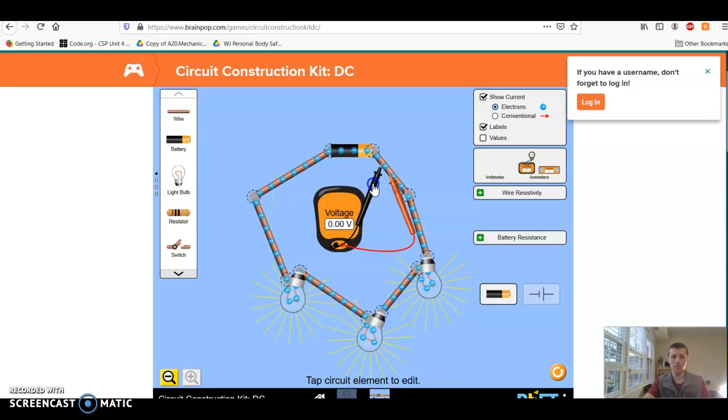Now, something interesting happens if I switch these two. You'll see I still get 20.5, but now it's negative. For our purposes, it's not usually going to matter whether the voltage is negative or positive. It just determines which way the electrons are flowing. So this is telling me the electrons are actually going this way, and I've crossed my wires.